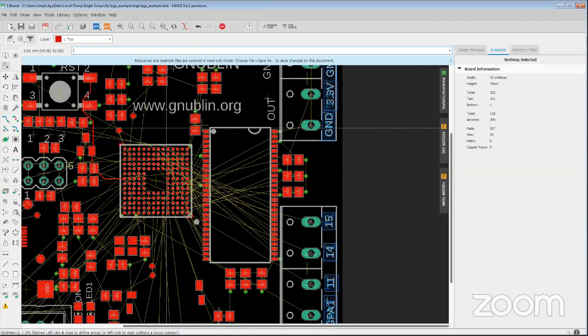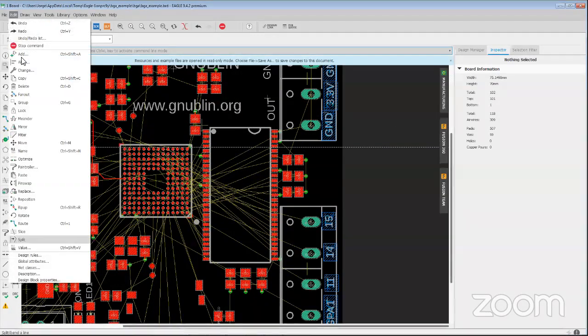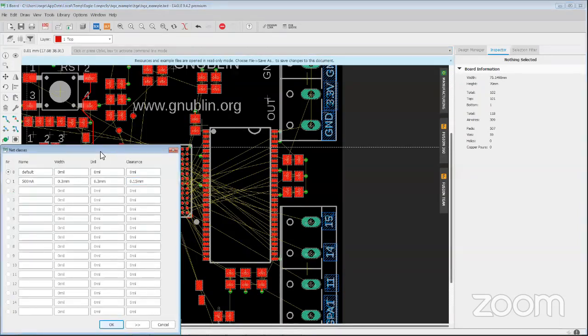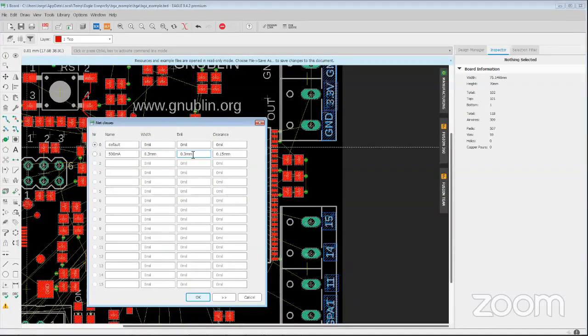Exactly. Did we cover net classes? We did not cover net classes because this was the auto router webinar, but we can show it briefly. I just wanted to bring up the net classes because the auto router, in addition to respecting your DRC criteria, respects net classes, which will override the criteria defined in DRC when they are larger and specified for a particular signal.